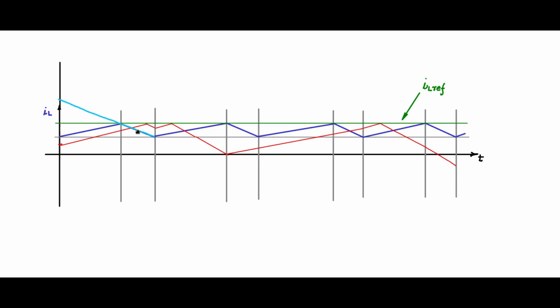Now the falling slope of the inductor here is minus V0 by L, or minus VB by L for the case of the buck converter. So we will use that same slope, continue it upwards. Now this is the slope line that we will use for this time period Ts. We will repeat the same slope line for every time period.